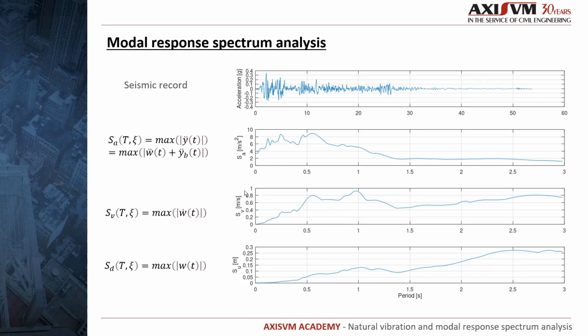At 0-second period, the structure is infinitely stiff. The structure is moving together with the base, so their accelerations are identical, while the relative speed and displacement of the structure are zero. As we can see, the spectral acceleration depends strongly on the vibration period, so basically on the mass and stiffness of the system. Also, depending on the natural vibration period, the system may be sensitive to high accelerations, velocities, or displacements.